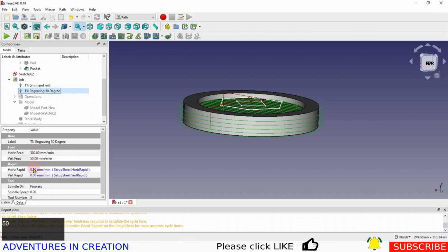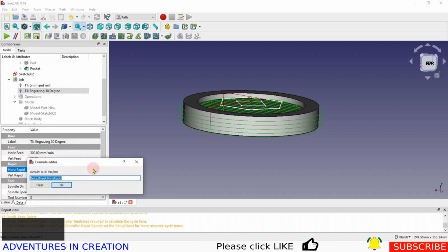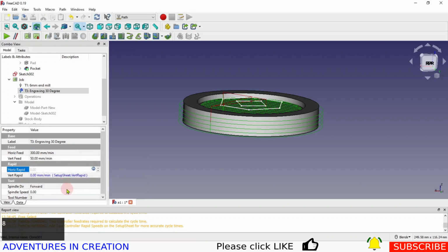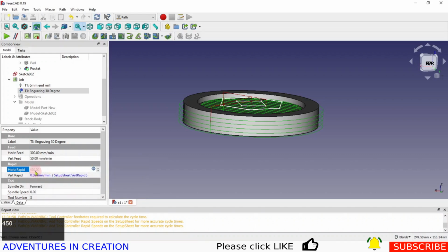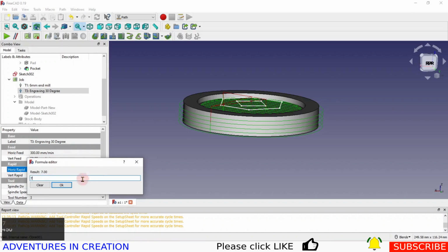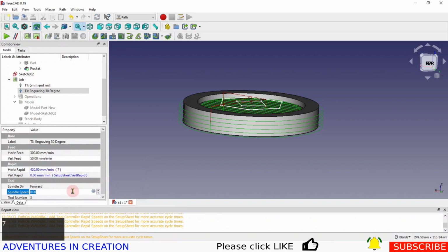And then my rapids. Now the rapids get calculated in some weird way. So the only way you can change it is you hit this guy. And if I say 8 and say OK and click somewhere else, you see how it comes in at, I'm not even sure what the calculation is it's doing. If I say do 450, which is what I really want it to be, it says 450. I click over here, now it says 27,000, not what I want. So I figured out if I say 7 or 8, I get about the right number I want.